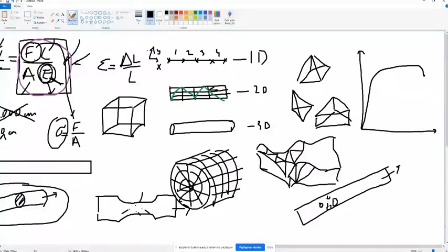So if you give the initial length of the system with the help of the laser extensometer, again the computer is now able to calculate the strains. So with all of them, you are able to calculate sigma stress, epsilon strain, and now